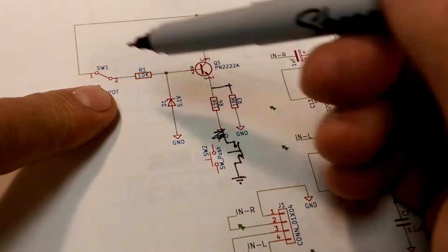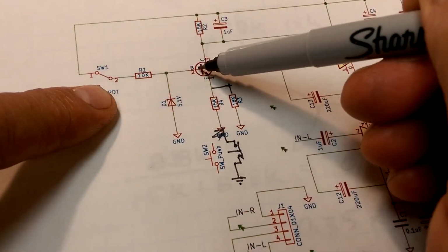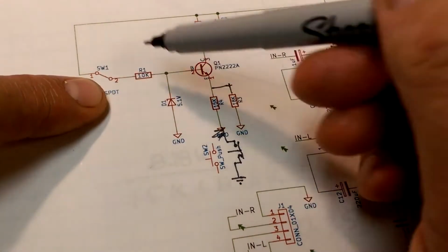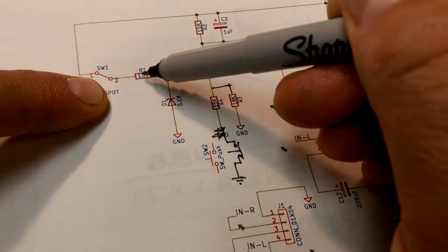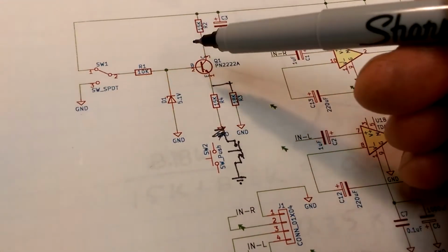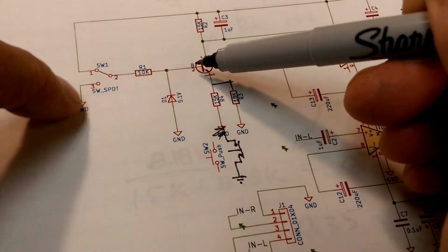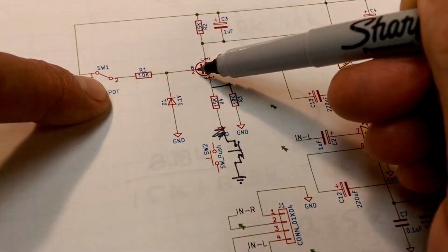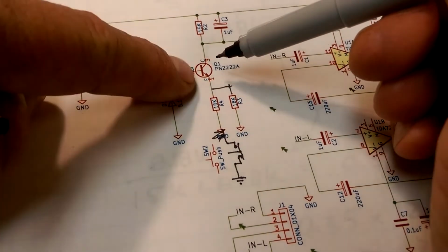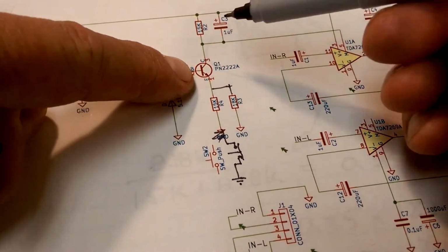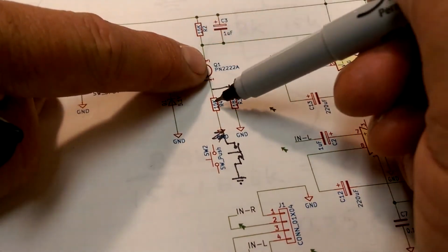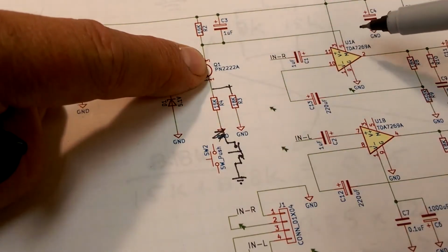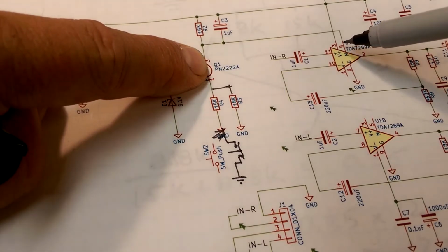That means there's no current flowing into the base of this transistor, so that means that it's off. But when the switch is in that position, this transistor is going to be biased upwards through this 10K resistor to VSS. So there's going to be some current flowing here, and we just have to make sure that this 10K resistor provides enough current flow to the base to make sure that this is in full saturation as it's turned on. When it is turned on, that makes these resistors into a voltage divider. And that voltage divider is adjusting pin 5.